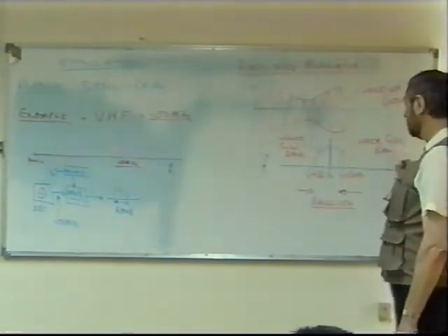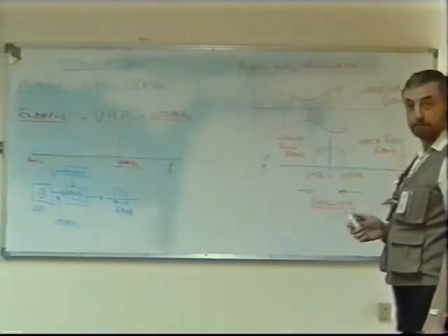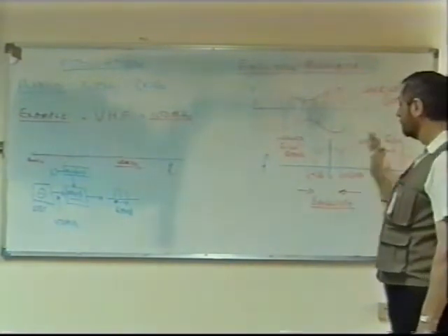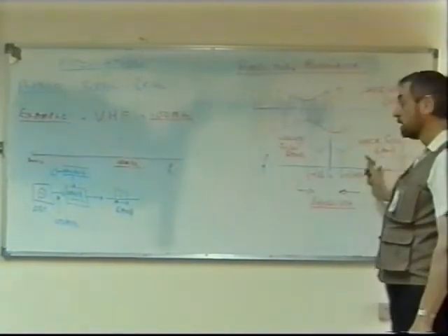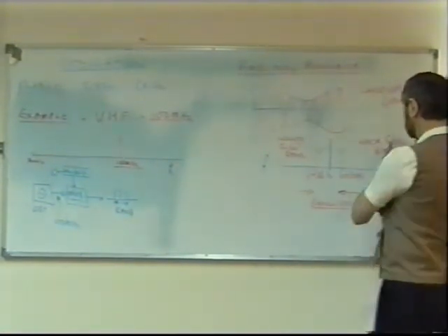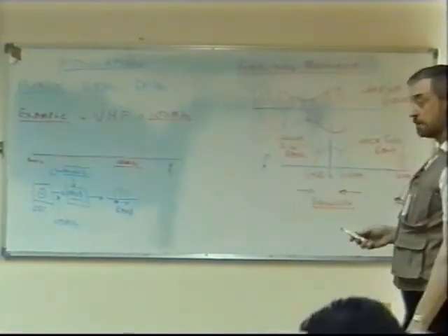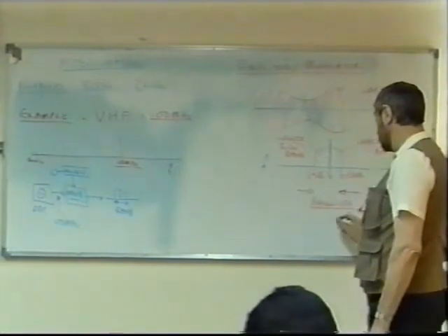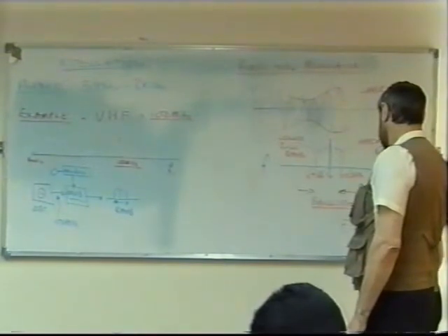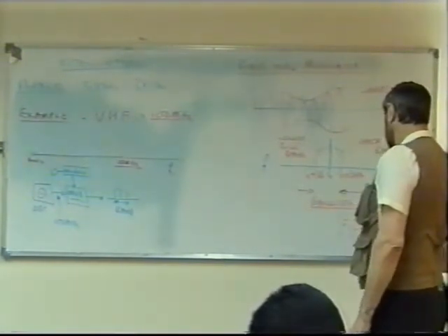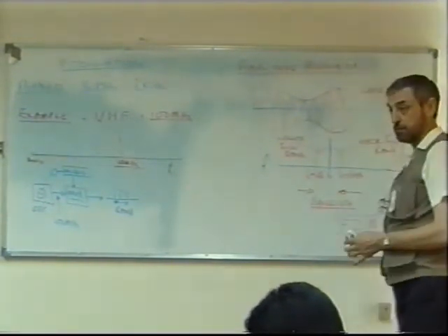Of course, what I've described here is frequency division multiplexing of the band. This is frequency division multiplexing, when more than one signal can use the same band of frequencies, but they don't interfere with one another, providing they don't use the same frequencies at the same time. Yes, at the same time as well, but this is what we call frequency division multiplexing, FDM. This is an example of frequency division multiplexing.